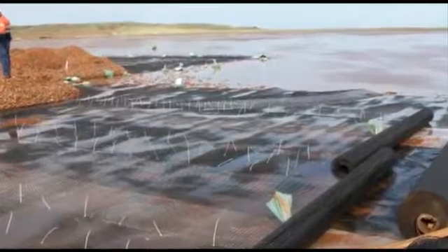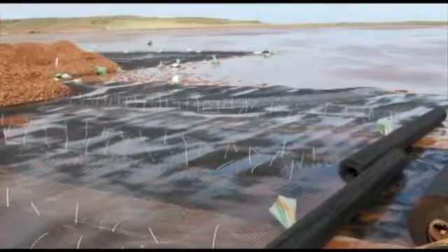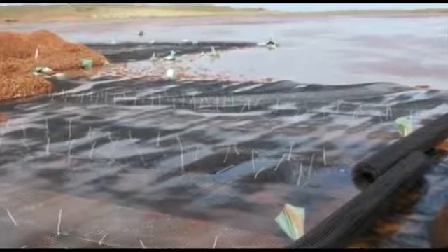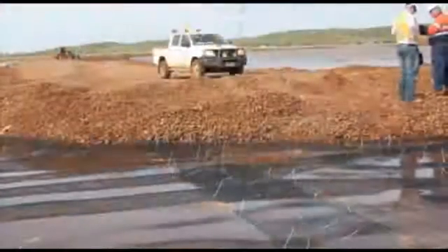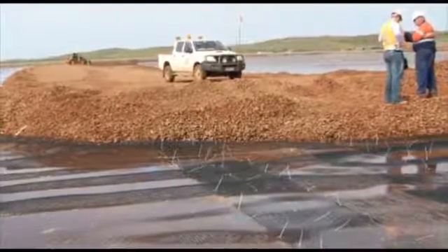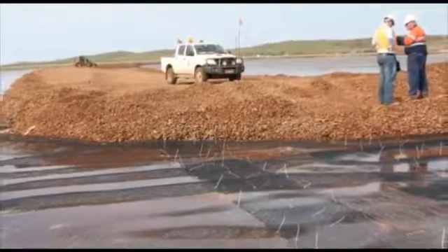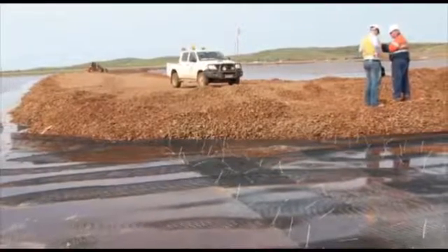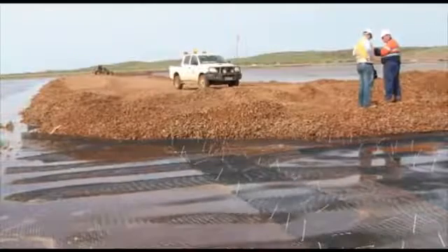Here is an example of a geosynthetic reinforcement layer being used at the base of an embankment being built on weak soils. The reinforcing layer helps strengthen the base of the structure and allows the structure to be built faster or at reduced cost compared to alternative solutions, such as deep excavations or piling, whilst remaining within the allowable settlements. Controlling settlements is a major part of geotechnical design.